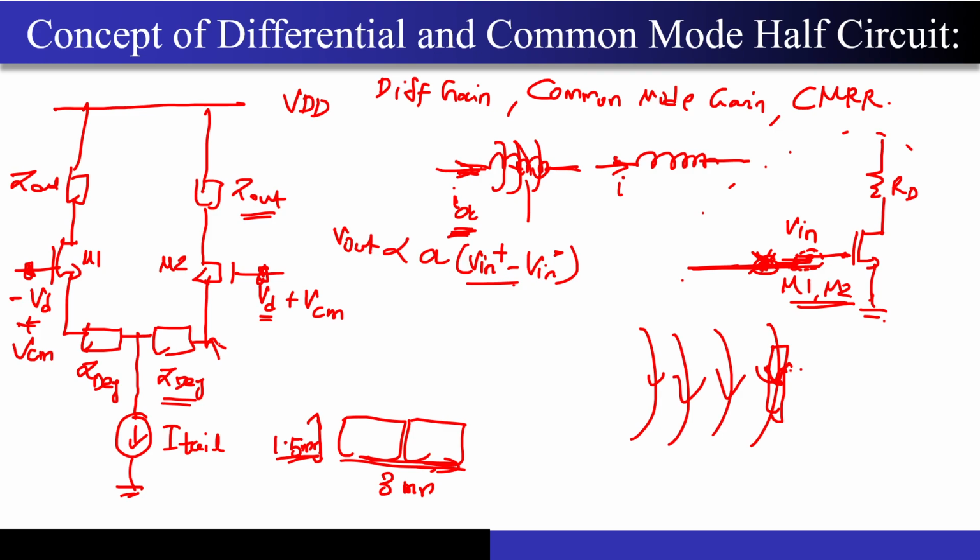And if you look at the papers that I had shown you in the first lecture, just go back to these papers and look at the baseband circuits. You will see the complete differential chain, right? Only at the end where you are going to connect the pad, that is the baseband output, you will see a single ended thing. But the rest of the processing, whether at the RF end or the baseband end, most of it will happen through differential circuits only. This is the importance of differential circuits. So now how are we going to work with this?